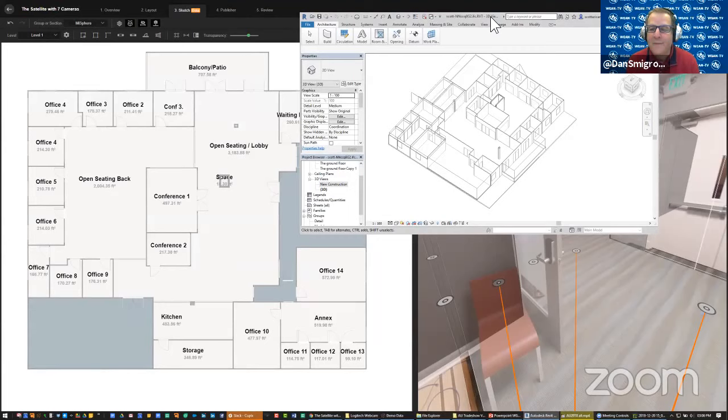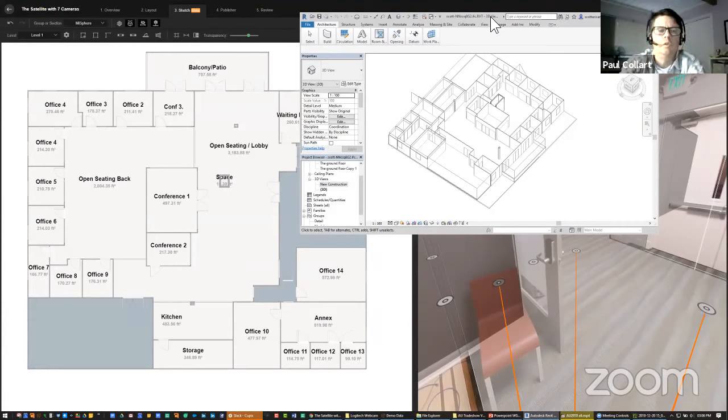I mean, it depends. And quite honestly, I'm not sure what most people are using to get that into Revit. They're probably taking the point cloud and bringing that into Revit. And what you do is you literally trace over it to recreate that in Revit. So it's a very similar type procedure, except we're just doing it in the 3D tour.